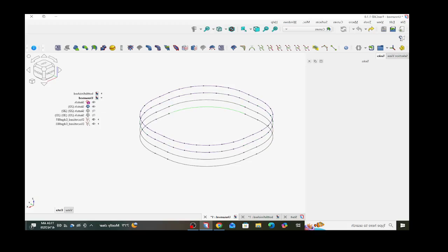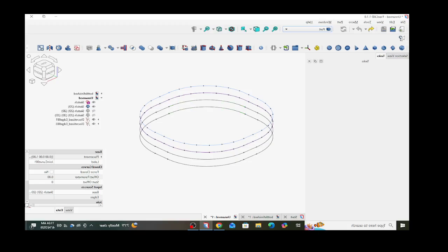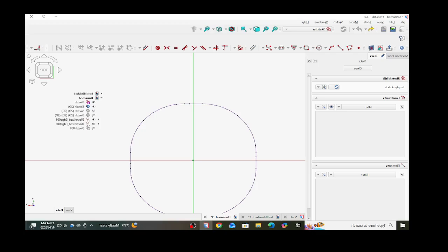Alright. Now I'm going to go back to the Part workbench for now. I'm going to click on our top sketch and click create a new sketch on the object's XY. We're going to hide all these old sketches in our join curve.